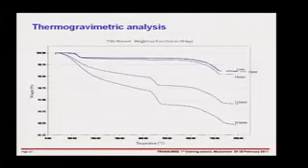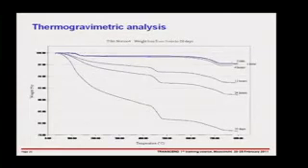Nevertheless, if we go on, we see that as we go to 24 hours, 28 days, the amount of water combined increases. You can see your scale is changing each time here, and between 24 hours and 28 days, we have about 2 or 3 times as much hydration.